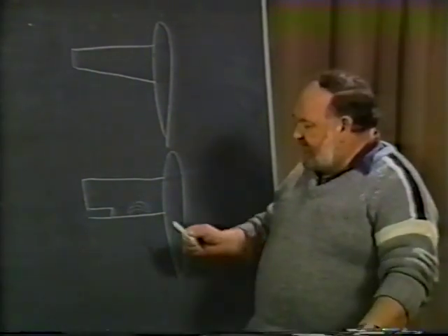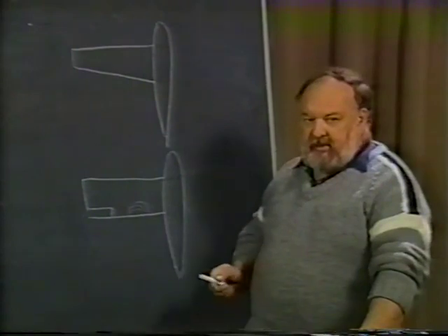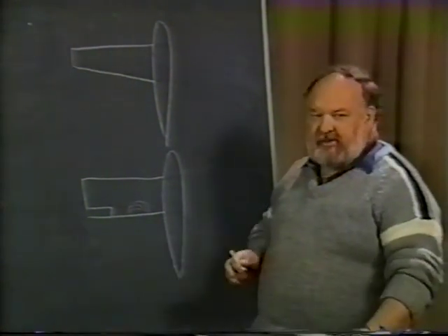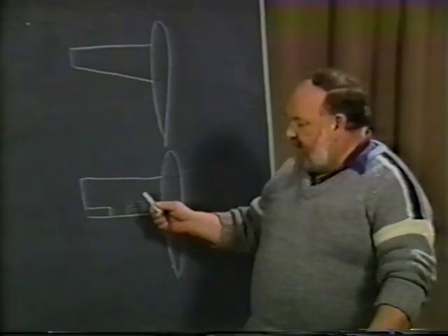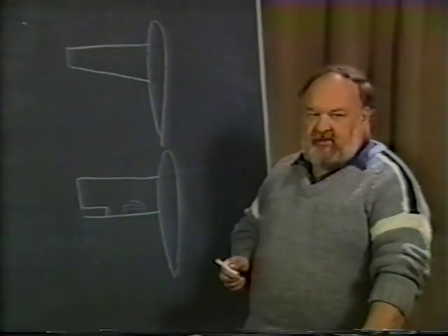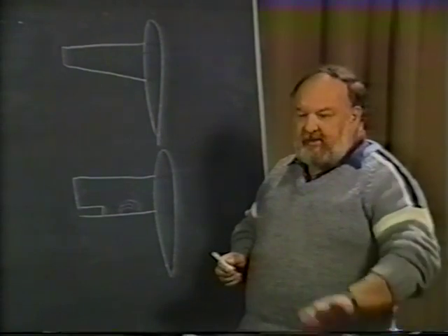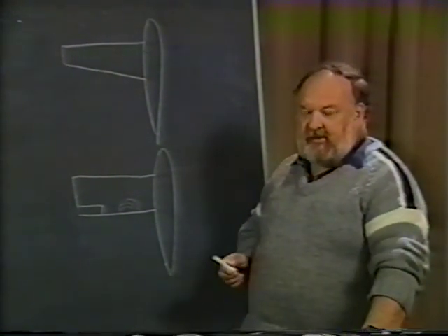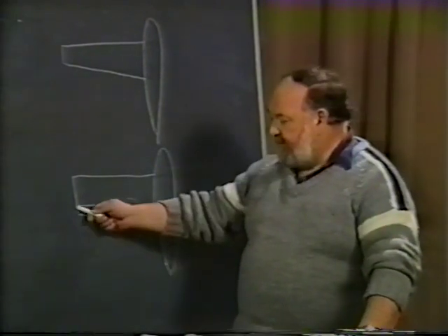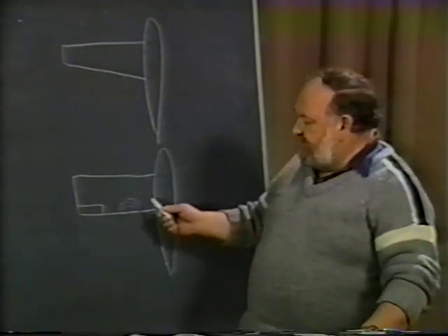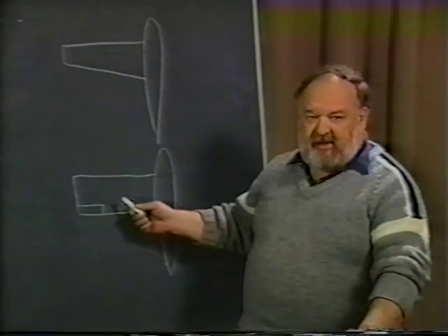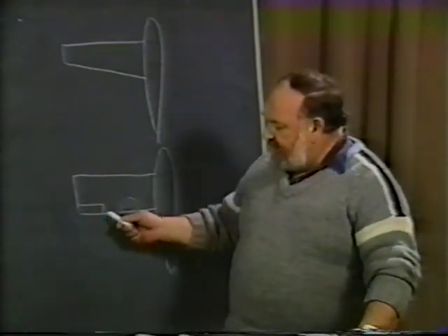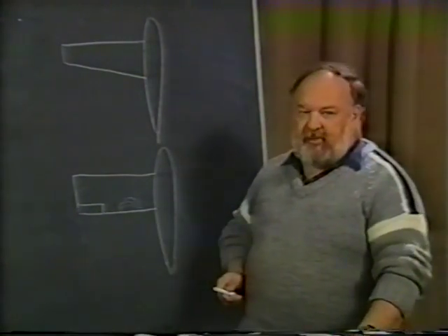If, on the other hand, it's outboard, and for any reason at all, you have just a little bit of yawing of the airplane or just a little bit of turbulence or whatever might occur, and one wing section, tip maybe, stalls before the other, the airplane will have a tendency to roll, and of course this can become the onset to a spin developing. So besides that aspect of it, you also would like to be able to have some roll control, lateral control, while doing this, and therefore you want to stay away from having the stall pattern begin out near the tip.